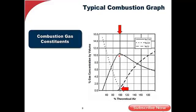Now, here I'm burning natural gas. The CO2 value at stoichiometric is going to be in about the 11% range. That's as high as I can go. If I was burning number 2 oil, it'd be up around the 14% range. But I'm burning natural gas here. So this is my CO2 level. Now, as I go to the left of the curve and I start to go fuel rich, you can see what's happening to my CO right here. It's beginning to increase. Got to be very careful about that.